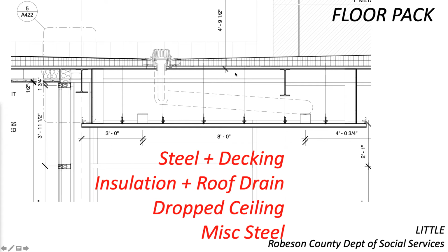Here's a floor pack at the roof, and we're not really seeing the evidence of the material that is supporting the roof insulation. Probably it is running in the other direction, so the corrugations are hidden from view, or they are very shallow, and that's quite a possibility. But you will see here, and I think what's important, is that the insulation is sloped, allowing the insulation and the roofing material to flow any rain collected water into a drain system that moves through the roof to the floor pack and down into a drainage system.